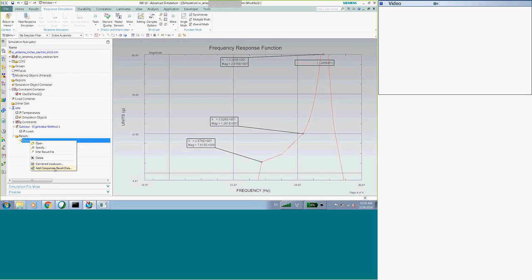Companion results. Okay, let me step back a bit. In any post, what you see on the screen comes from the OP2 file or the results file, whether ANSYS, Abaqus, whatever; the entry is always the main results file, and that's what you see. The companion file, however, does not need to have geometry.